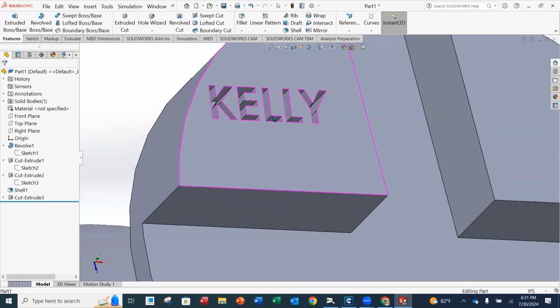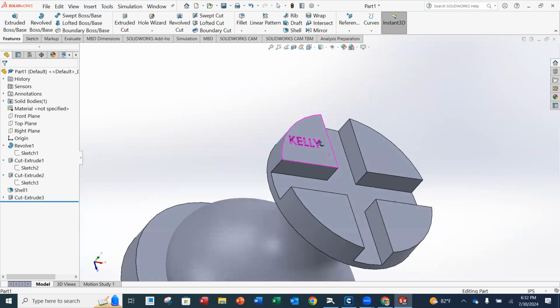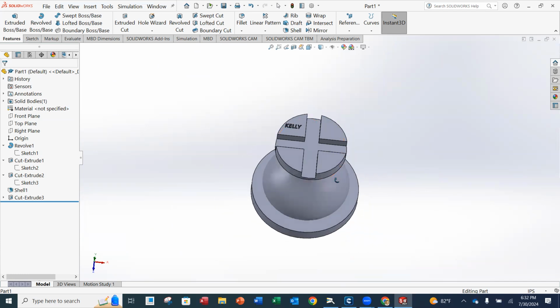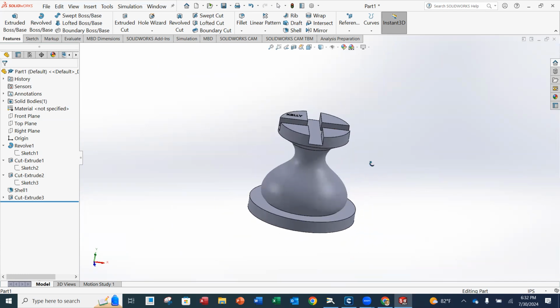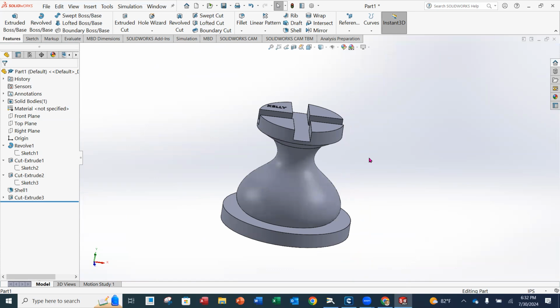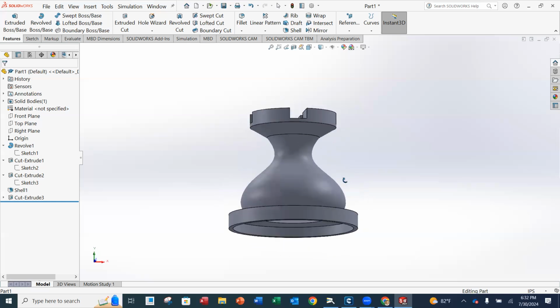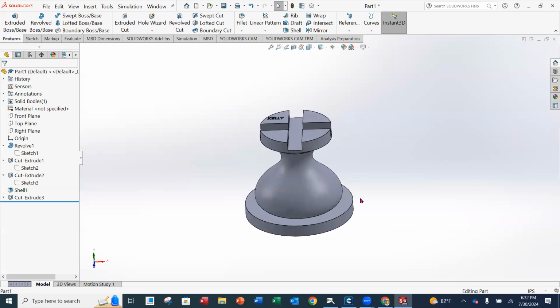All right. So this is only a demonstration of a couple little things, including maybe a couple things that we haven't done. So using that rotate function, if you wanted to create a chess piece looking thing, adding some text, or if you wanted to hollow out, I wanted to show you how you can use that shell command and then specify that wall thickness.